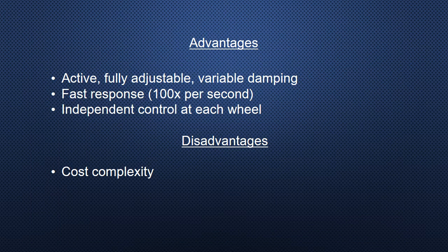Advantages: they're active, as in they work in real time. They're also fully adjustable, as the amount of damping can be changed by changing the magnitude of the voltage, and they have variable damping, as the magnitude of the damping can be varied according to the size of the bump, or it can vary according to the situation.